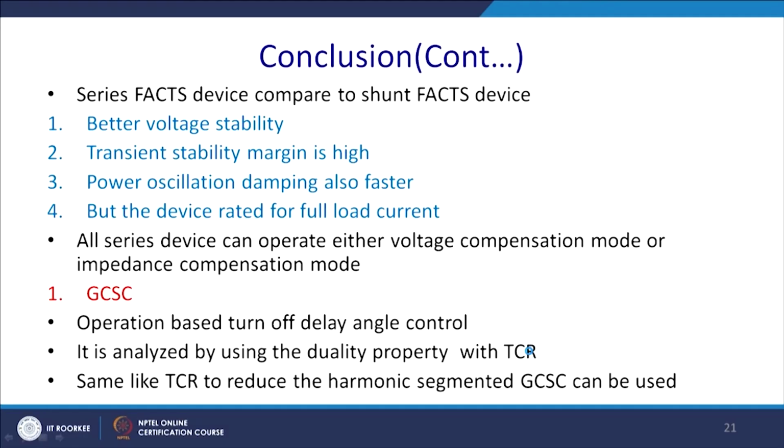So, what can the series FACTS device do? It provides better voltage stability and transient stability margin. We have all discussed those issues in series compensation, power oscillation damping, but one of the basic disadvantages is that the rating has to be in series. So it sees the total voltage and current rating. The device will be rated for the full load current.